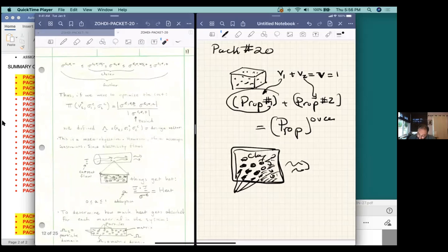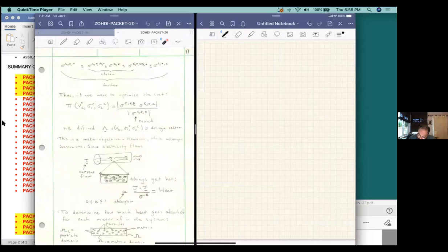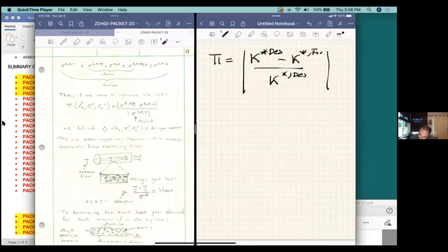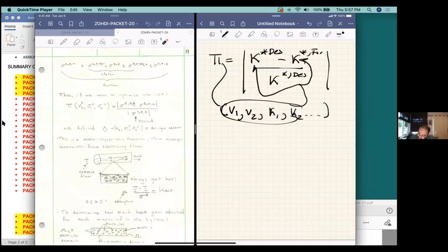So the purpose of that assignment, which isn't the last one, is simply to say, look, if I have some desired, for example, bulk modulus, and I have my formula, which I hope is relatively accurate, I need to somehow figure out how to design the parameters that are in this model. The cost function has, for example, the volume fraction of material 1, the volume fraction of material 2, the bulk modulus of material 1, the bulk modulus of material 2, and so forth. Those parameters dictate everything about how this thing is going to achieve that, by messing around with these formulas.